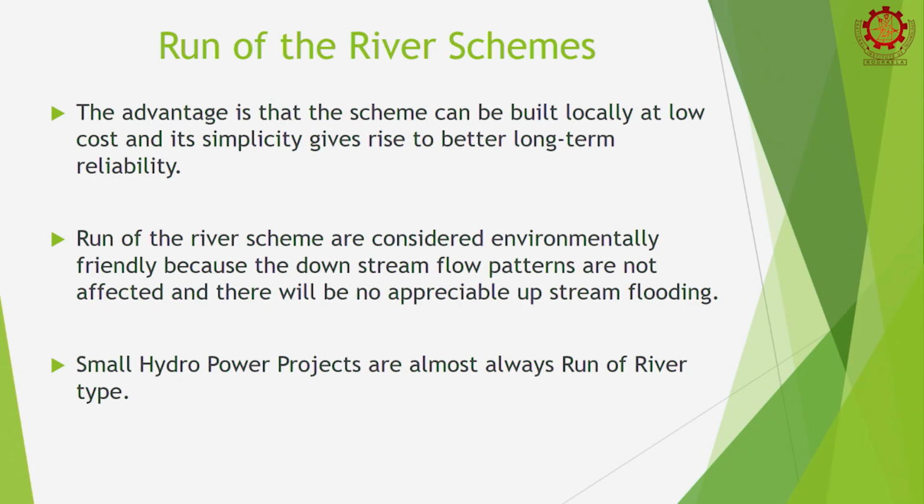And so, they are very environmentally friendly, and downstream flow patterns are not affected, and there will be no appreciable upstream flooding. When you block a river and prepare a dam and collect water, there is a backwater level. So, if you construct a dam and collect water, your backwater curve, earlier the river was flowing at this level, now you raise the water level. Therefore, the river's backwater level will go up in the upstream to maybe a few kilometers,